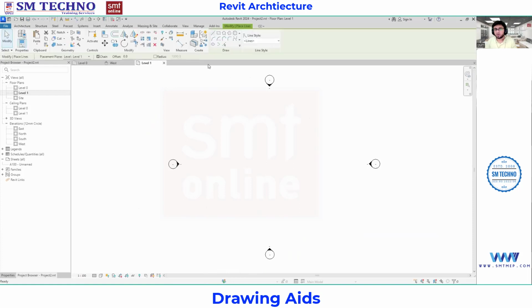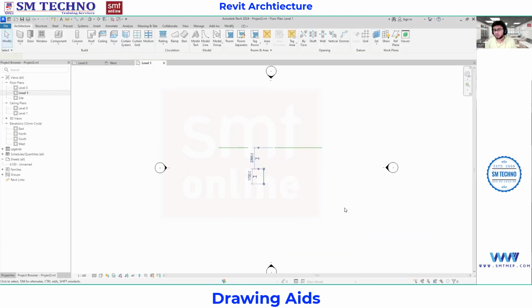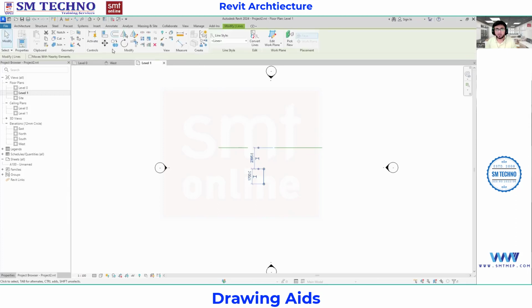I'm going to draw a line over here, and I want to place this line exactly at the center. So what I'll do is go with the option of move from here. These are nothing but the modifier commands we have; I'll explain them later. This is mirror. This is offset. This is copy. And this is the move we have.